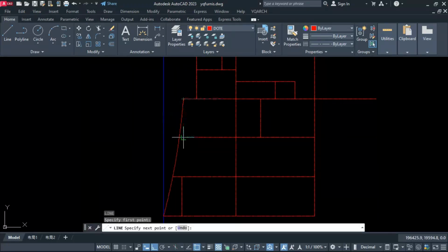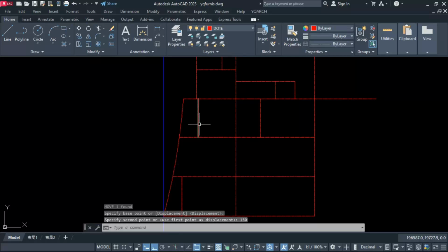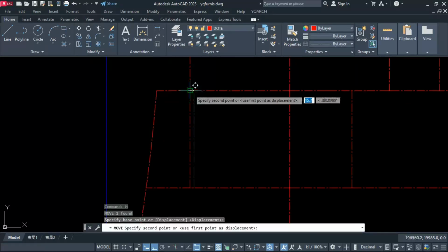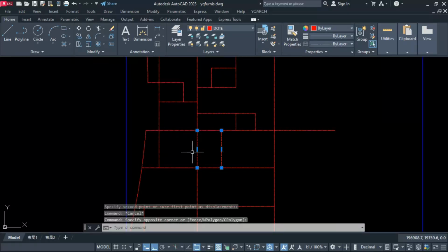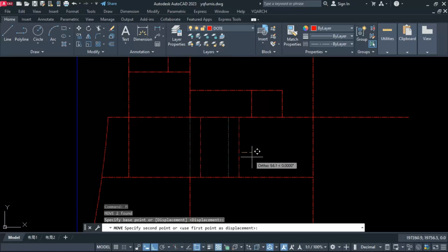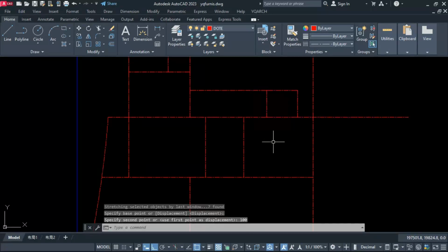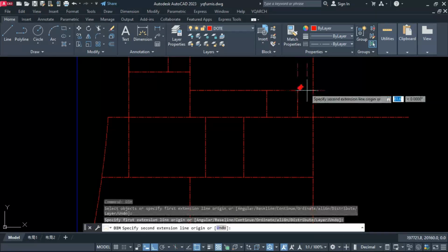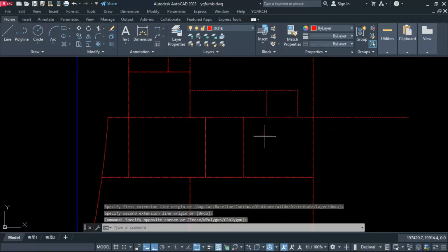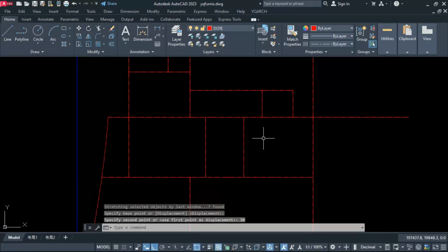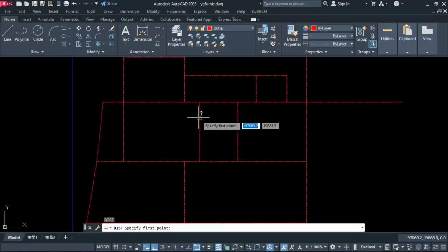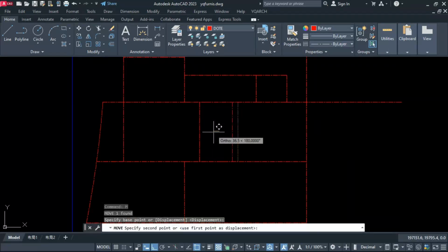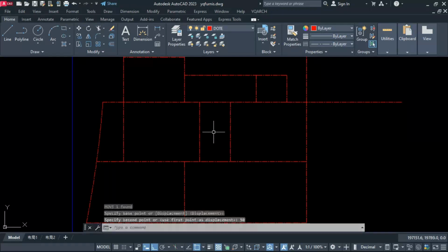Let this straight line move here 150 centimeter. Okay, let this point, no problem, and let this here, this will cover our kitchen. We'll keep this one 100 centimeter. Let this 100 centimeter also. Minimum you can keep entrance 130 centimeter, 120 centimeter. You must keep that much corridor spacing for flat entrance. This wider kitchen. So here we will provide attached bathroom, right?